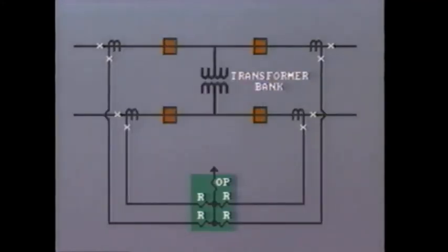Here's another example of multiple connections to transformers. This single line diagram shows that the primary can be fed from 2 different sources through separate breakers. Similarly, the secondary can be fed to 2 different loads through separate breakers. In other words, there are 4 connections. We must have 4 CTs, and these will be connected to 4 separate restraint coils on the differential relay.